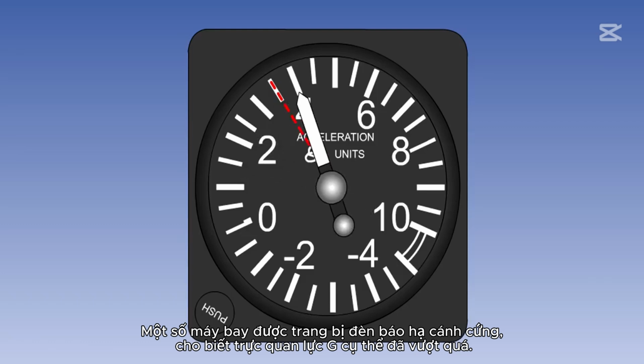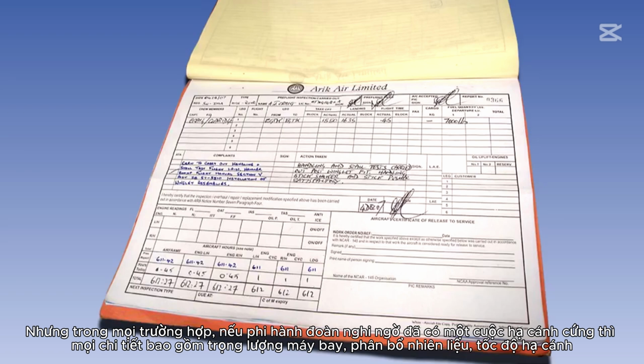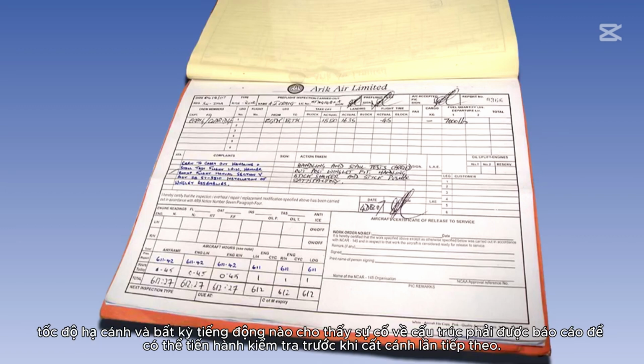Some aircraft are fitted with hard landing indicators, which give a visual indication that specific G-forces have been exceeded. But in all cases, if the crew suspect that a hard landing has been made, then all details, including aircraft weight, fuel distribution, landing speed, rate of descent, and any noises indicative of structural failure, must be reported so that an inspection can be carried out prior to the next takeoff.